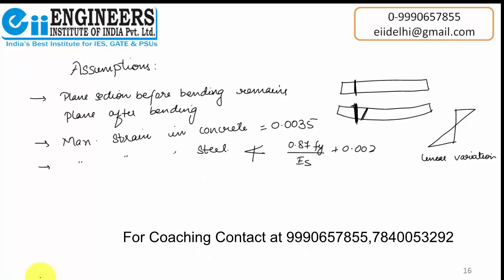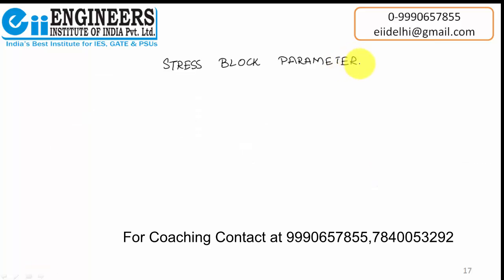Last and one more, tensile strength of concrete is ignored. We assume that concrete does not possess any tensile strength, all the tensile forces are taken by steel. Now, going to the main and very important thing, the stress block parameters of concrete. Since we have considered a singly reinforced section,